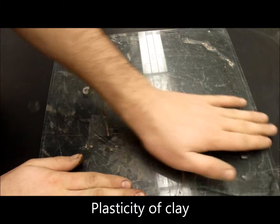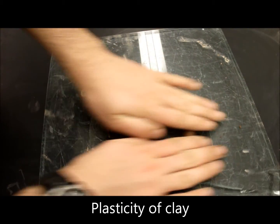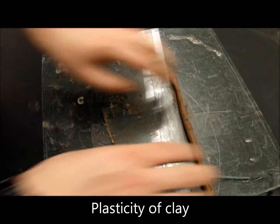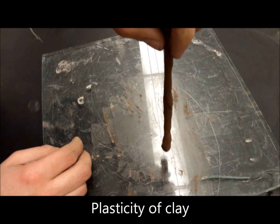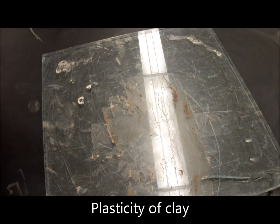until the soil crumbles before it can be fully rolled. At this point, ball the soil up one last time and knead it until it crumbles. For further analysis, you may mass the sample and place it in an oven for further water content testing. These results will be used in analysis of the soil's toughness, which refers to the stiffness of the soil as it reaches its plastic limit.